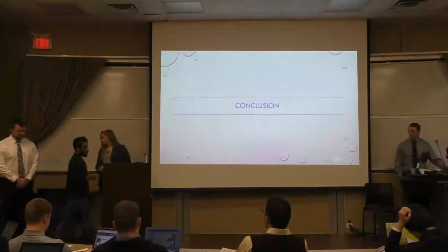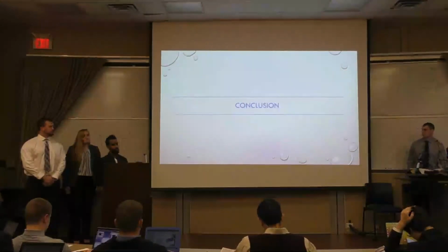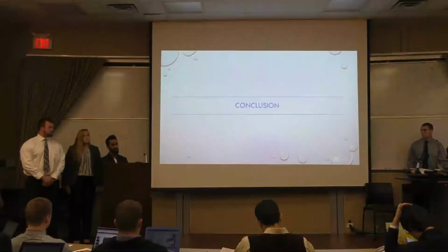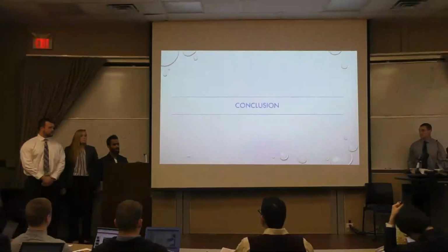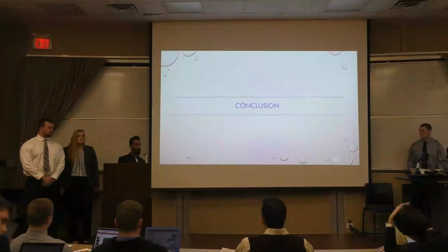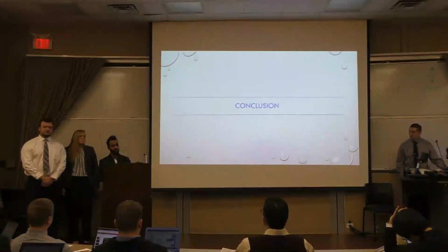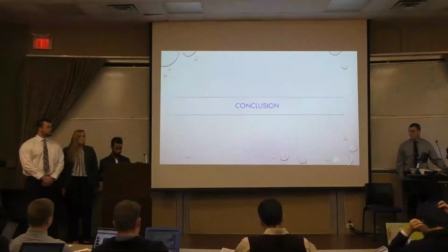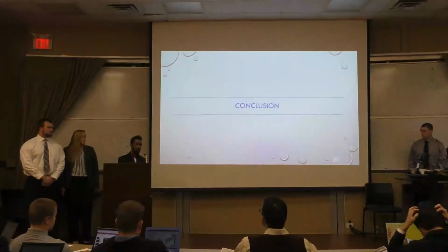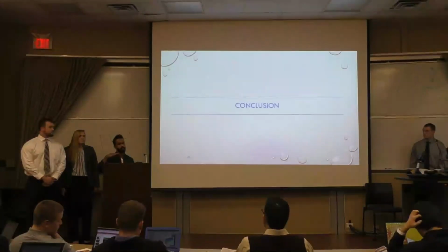So in conclusion, the process of cyclic steam injection has three stages, which are the steam injection, soak phase, and oil production phase. And this process has a higher success rate than the other techniques due to improved sweep efficiency and reduced cost of directional drilling.